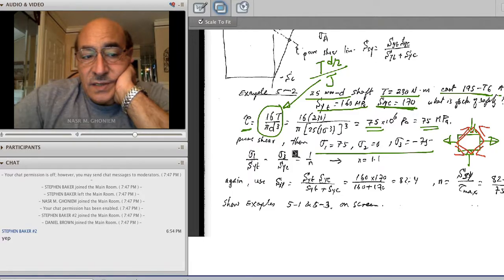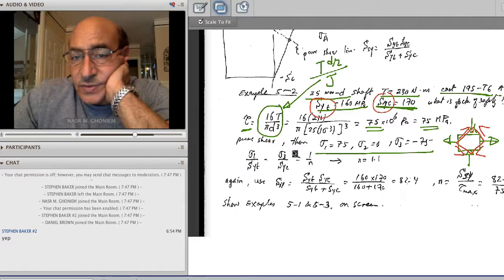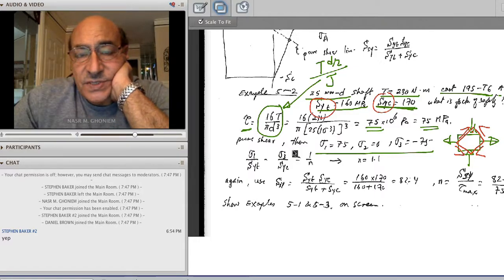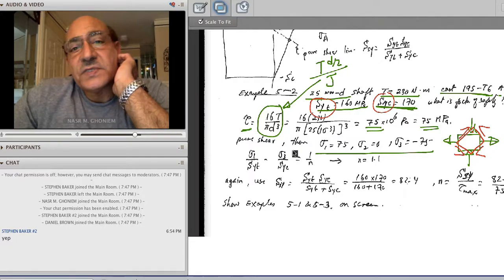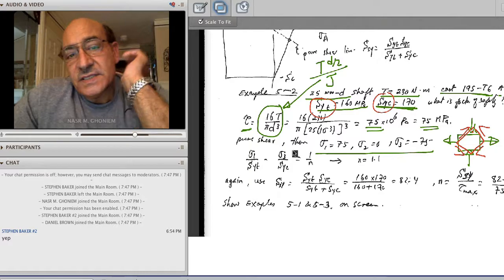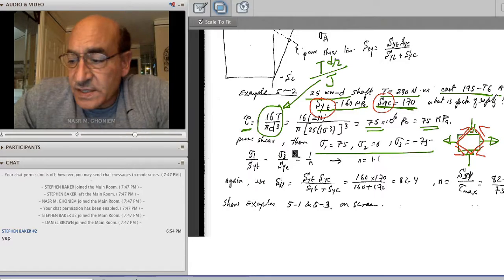Okay. All right. So with that, since the strength in tension is slightly different from compression, I could have used the standard maximum shear criterion, but here, since I have two different values, I might as well use the Mohr criterion, called ductile Mohr.